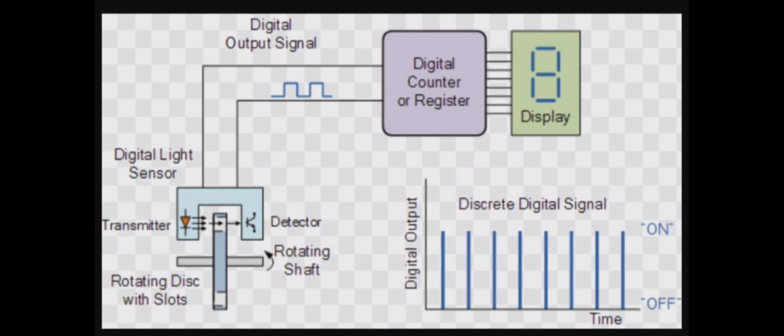Obviously, it has a mechanical contact, so after getting the triggered signal, it will take some time to energize its coil, as well as time to complete the contact, and then for the coil to de-energize. It means it will take a few seconds to operate the output. So it is used for slow switching applications.